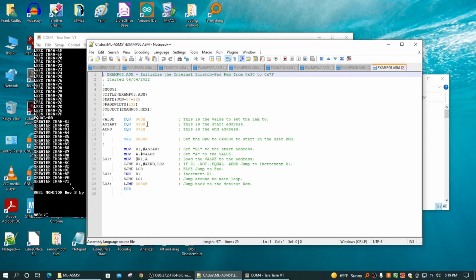Anyway, I'm going to write a value, and the value I want to write is 00. I just want to clean that, initialize that RAM, which is a good idea before you run a program. I believe a lot of the compilers do that, but when you write in assembly, you don't do it. When you first power up, the processor goes to basically any place.